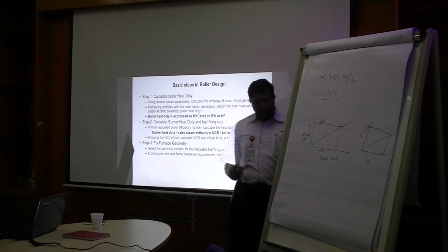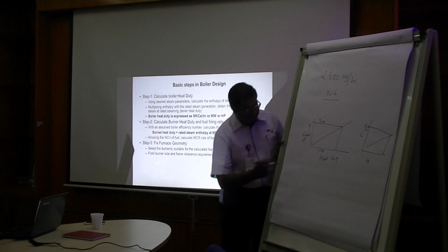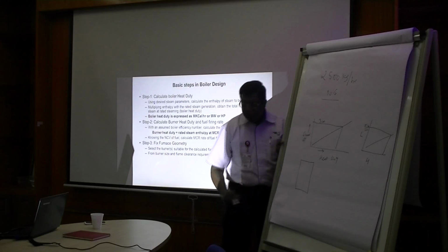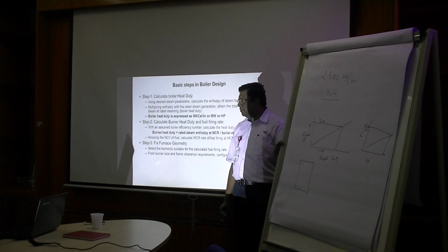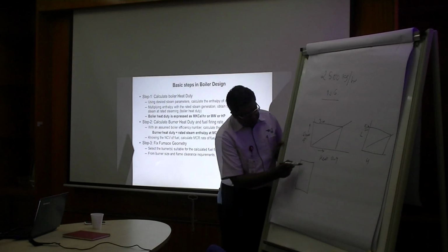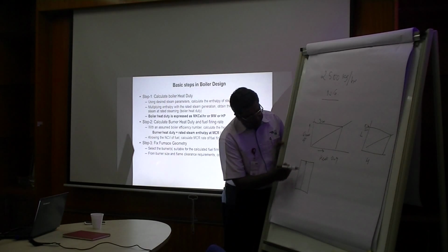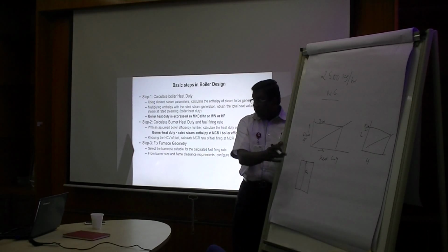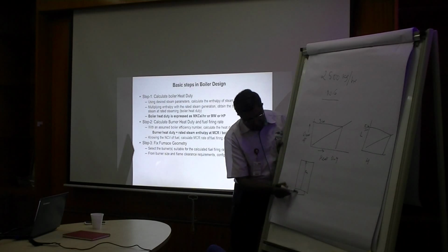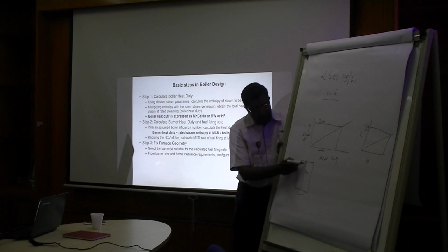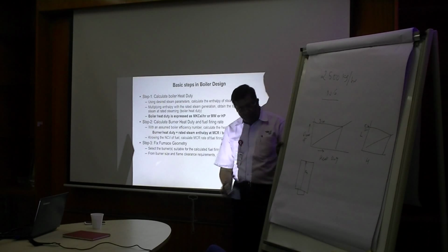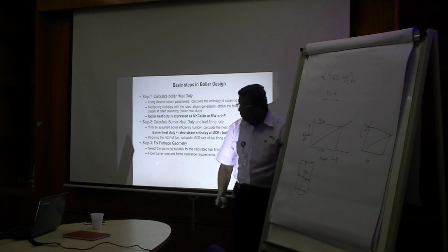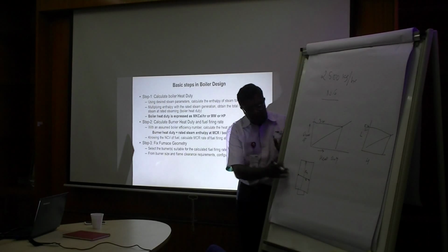On the same page still, because we have to be environmentally friendly, now you draw the plan view of your furnace, in which you know that the flame is going to be 5 meters. So the depth of the furnace in the plan view will be, if this is your burner, minimum 5 meters just for the flame, and minimum 3 meters for the diameter, flame length and flame diameter.